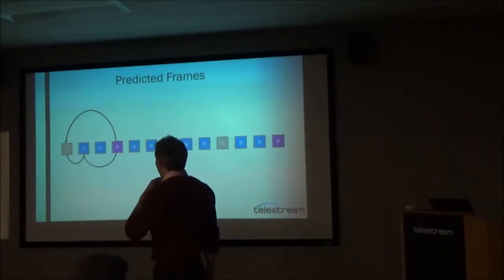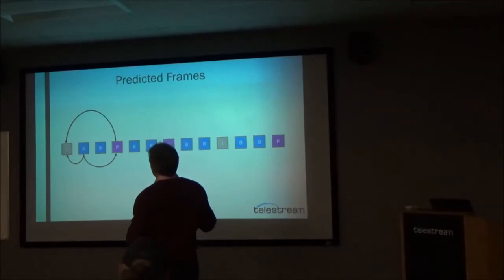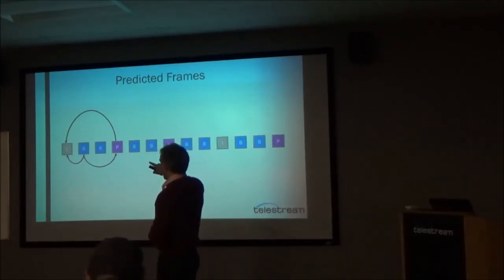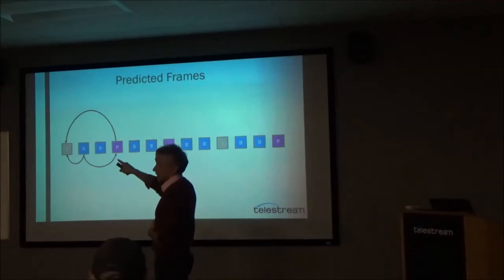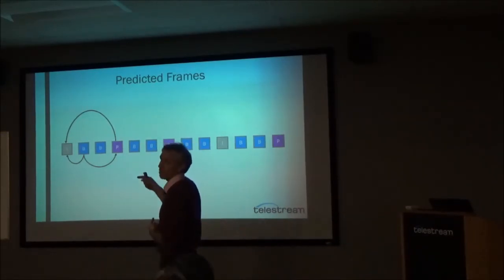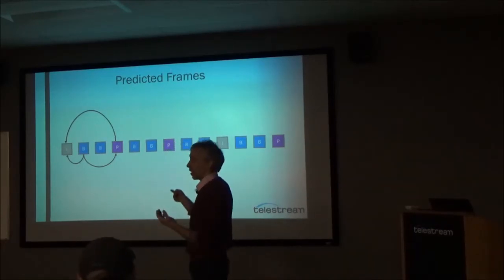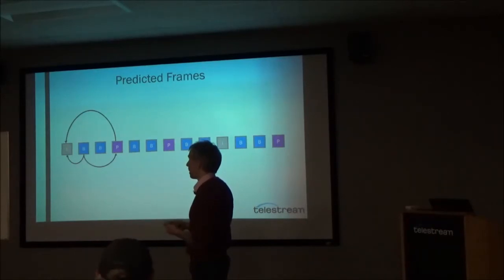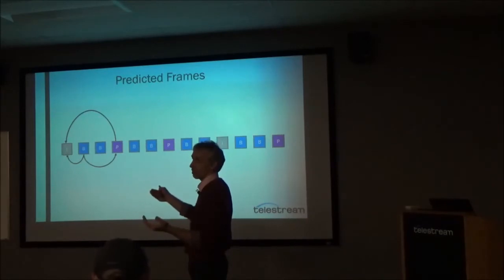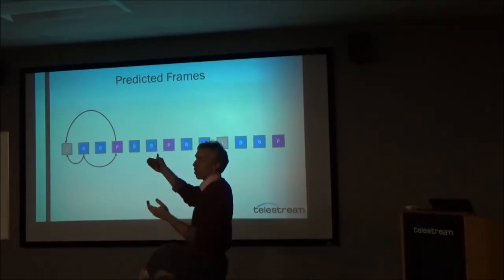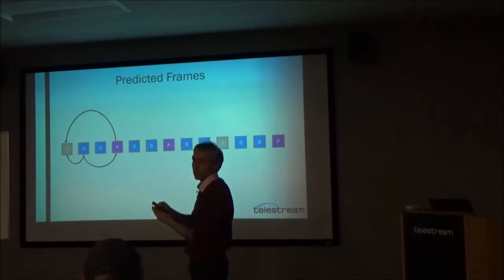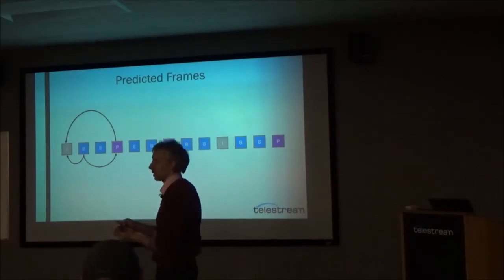And then we have these B-frames, which are bidirectional predicted frames. And what they do is they are allowed to use motion vectors that point either previous in time to the I-frame or forward in time to the P-frame. And it may be that it chooses one or the other because there's a good prediction in one of those two directions. Or it may be both, that we don't have a good match in either the I-frame or the P-frame. But by combining something from one and something from the other together, we can form something that we can use as a prediction for our blocks.